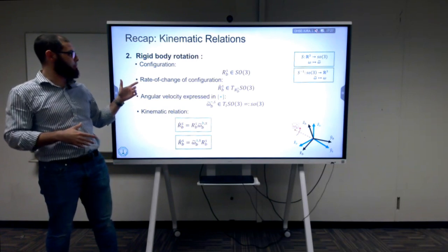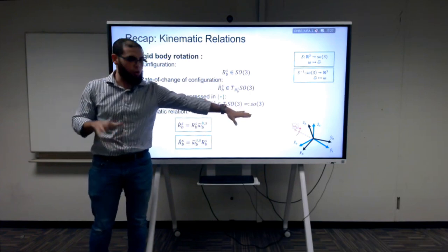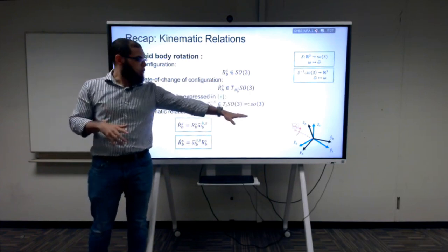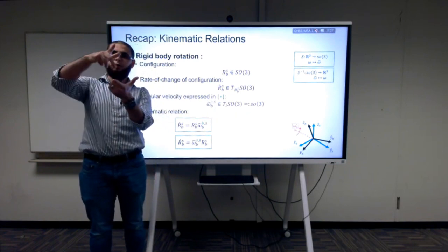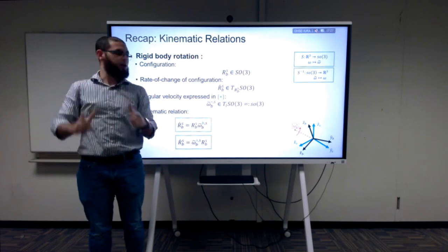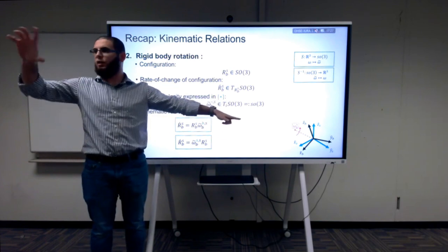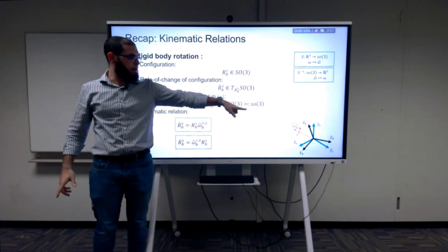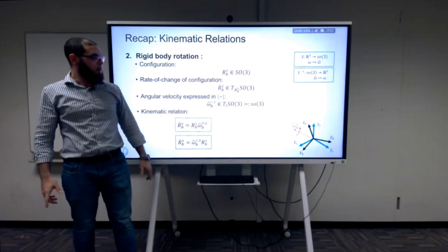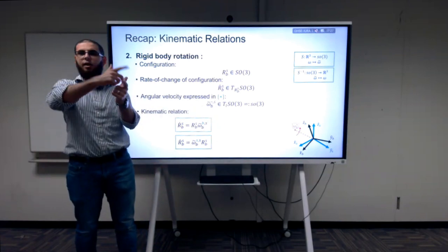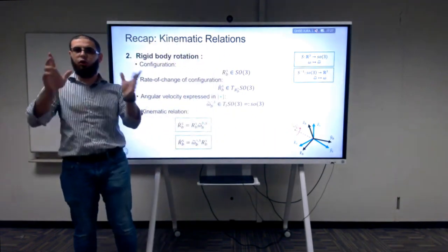We don't have this vector space structure. The configuration, as we mentioned, is given. Now we're discussing only the rotation part. Okay? So we have one frame. Now we need to talk about frames. So now we have the orientation of one frame with respect to the other. The frame that's moving, and it's fixed to some body that's rotating, we call frame B. And then we have one that's fixed, frame S. And this frame B is rotating around some axis. This axis here, we just denoted in red. So you all visualize it, right?